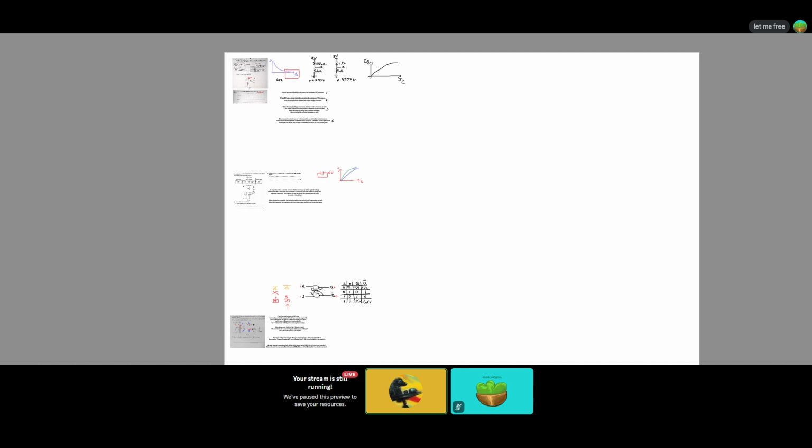So to summarize, analyze what's going on. If it's a circuit, analyze the circuit. You can actually circle some sub-circuits, like for example a voltage divider, an RC circuit. Then state some facts relating to the circuit. Then figure out what you want. To figure out what you want, either be very smart or you can try to work backwards to see how you can get what you want. So that's pretty much a 3-step plan.